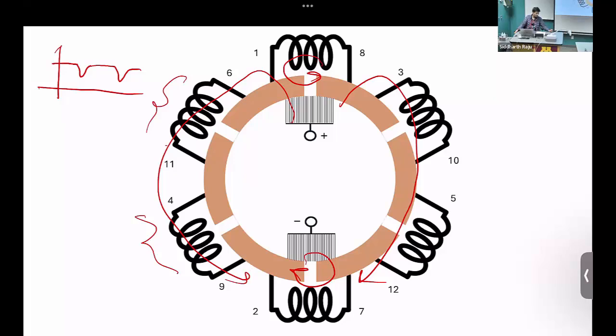Is the current that's split up into the 2 parallel paths still roughly 10 amps each? Yeah, it will be. Not roughly, it will be exactly 10 amperes, because each of these coils were previously carrying 10 amperes, and these are inductive coils. If nothing else changes, if the contact isn't changing, they are going to continue carrying the 10 ampere. Will the shorted inductor drop? The shorted inductor current will start to change.